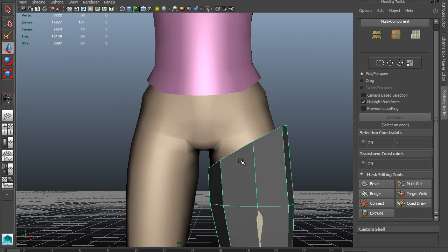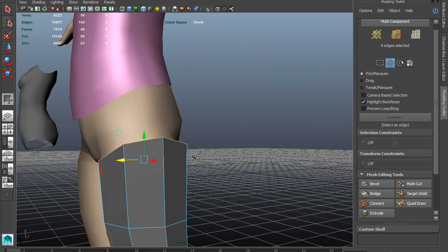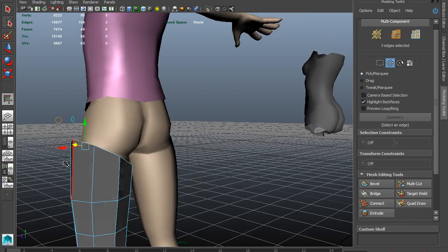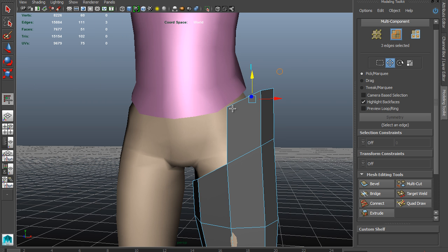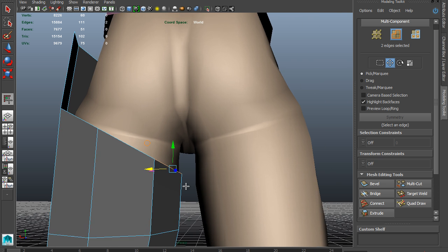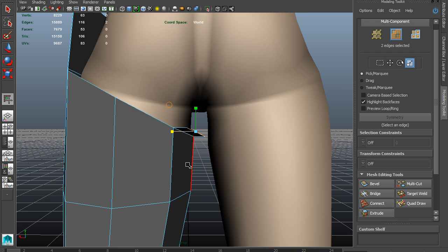Now from here, we just need to do edge extrusion. What I'm going to do is just do the front, the 2, 3, maybe, yeah, 3 sides. Edge extrude that straight up. Okay. Inner loops, extrude straight across, and then flatten them.